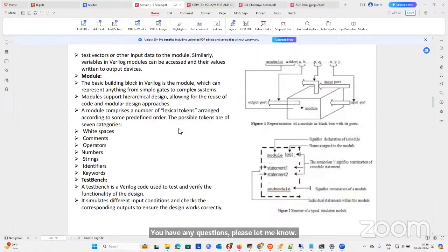So now we will understand how Verilog programming starts. In C programming, what will we do? We include stdio.h, printf, hello C world. The same way we have void main; in Verilog, module, adder, and inputs and outputs, and some statements for computation, and next, end module. So similar, I'll write a code for C and Verilog in comparison.